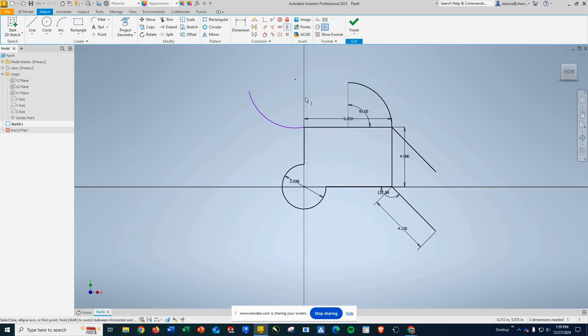I'm going to pick a vertical constraint, and vertically constrain this point over the endpoint there. So you can see that lines that up. I'm then going to use dimension to constrain this point vertically above that. You can see I clicked two different things at 2.5 inches.